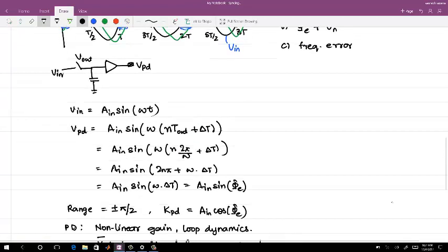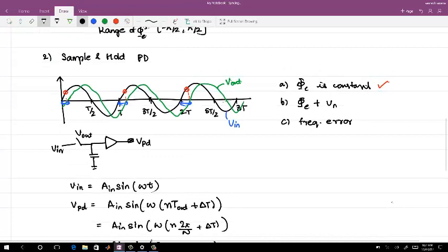So if it has all this, what is the good thing about this phase error detector? I can say that this is used a lot these days to have a very energy efficient design. Means you have a separate loop to bring the frequency within range or very close, and then for the phase error correction, you just use this.